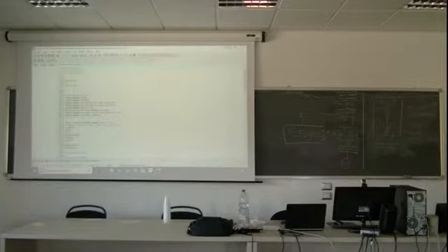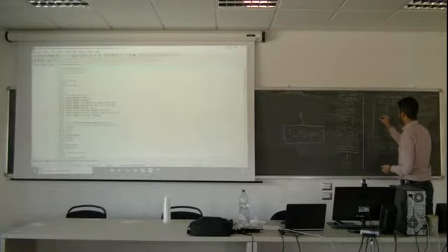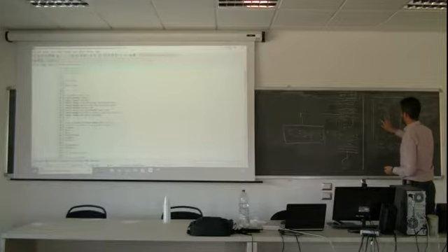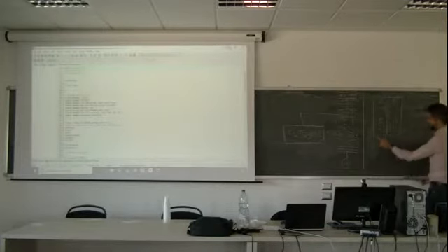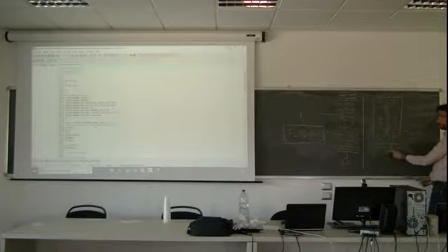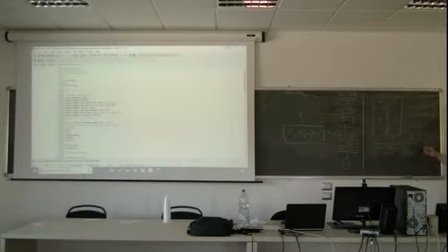Yesterday we talked about how to deal with homogeneous grids. I had a film and I divided it with the same delta R. Here we will have 2 delta R's. Here 1. Sorry, delta X because it's Cartesian coordinates. And here 2. Actually, this thickness is 5 centimeters, this thickness is 10 centimeters. And I want to use 10 nodes here and 10 nodes here, or whatever, or 100 or 1000, up to you. I don't care.